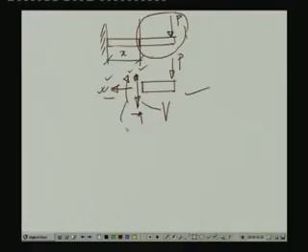So, at any cross section we take in this beam member, we get some stress resultant which will hold this particular part of the body, which is freed from the whole body, in equilibrium under the action of the load. Those stress resultants which act in the vertical direction to equilibrate the vertical forces, we call the shear forces, which are the internal stress resultants. Those acting in the horizontal x direction, we call the axial force, and the moment which resists the effect of the transverse loading in terms of bending, we call the bending moment. So, the stress resultants that will be acting at a section are the shear force V and the bending moment M.